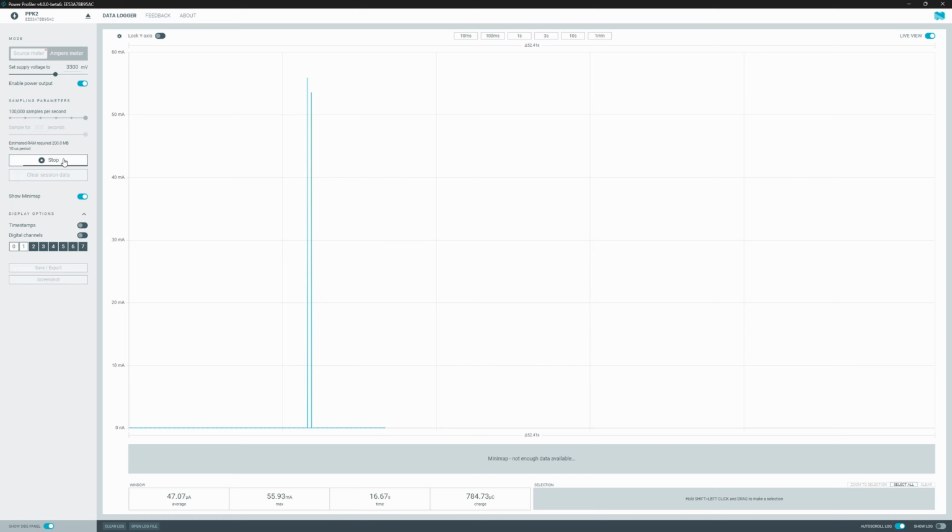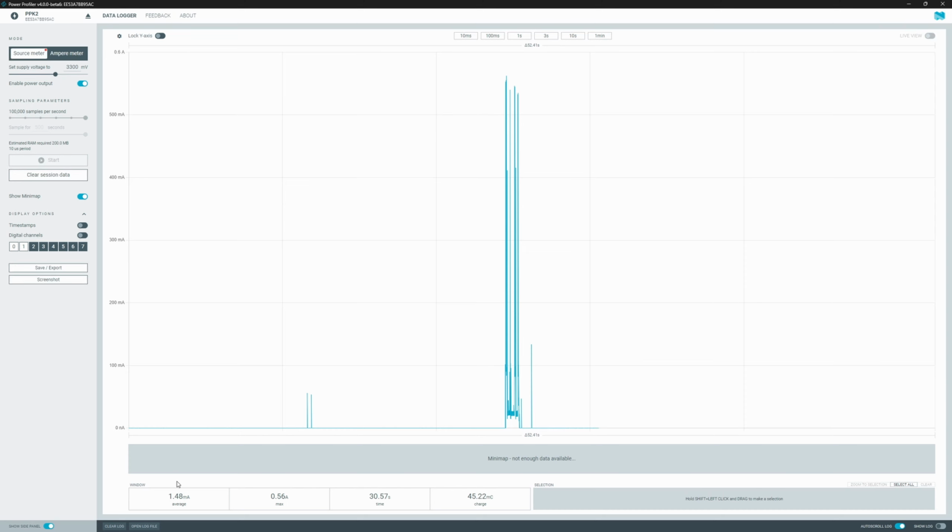We can see some weird wake-ups here which are not the actual data reporting, but I will explain that in the deep dive section at the end of the video. So here we are close to 30 seconds and now we have seen the reporting, which is much shorter than in deep sleep. And now after around 30 seconds we are at 1.48 milliamps in average.